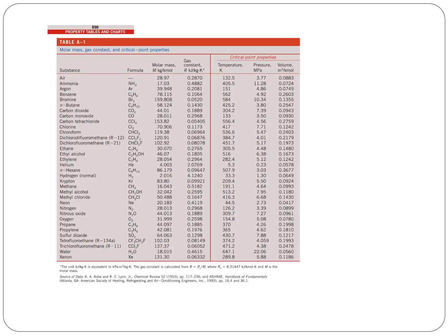Okay, so this is appendix 1, very handy, which gives you the value of the gas constant depending on what gas you have, and also the critical properties that are required. This is for the temperature in Kelvin. Again, be careful about the units. Pressure is given in megapascal.